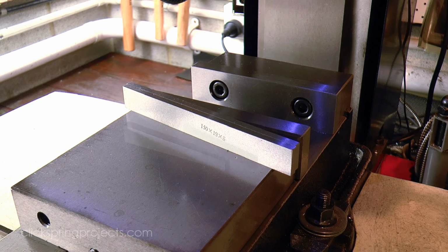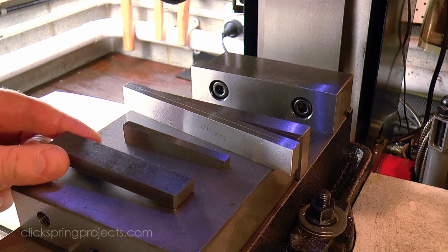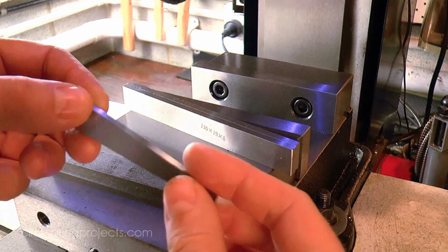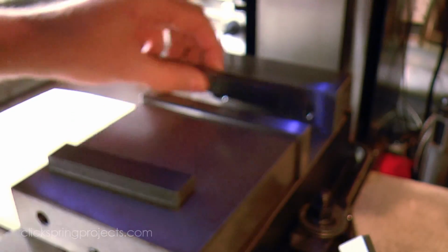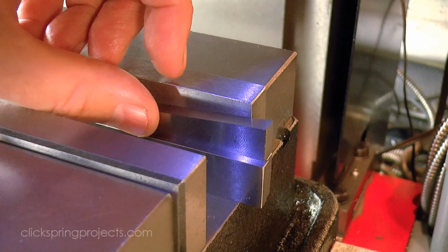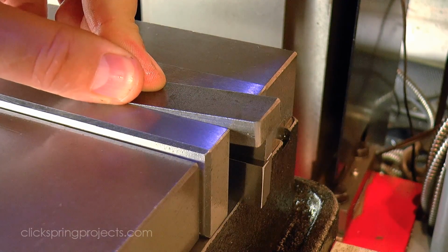But another important dimension is the slope of the small platform on the end of the shank, upon which the button cutters will rest. We'll be using 5 degrees, so this means that the buttons will be tilted forward by 5 degrees when the shank is mounted horizontally in the tool post on the lathe, giving a maximum of 5 degrees clearance at the front of each button.